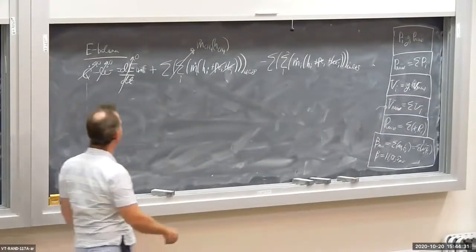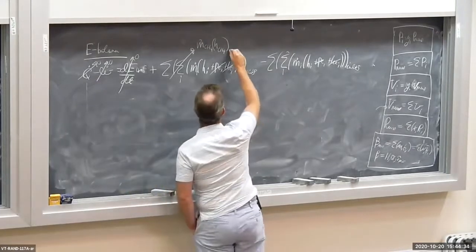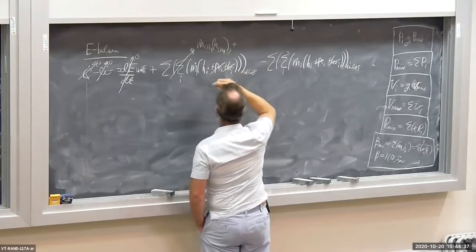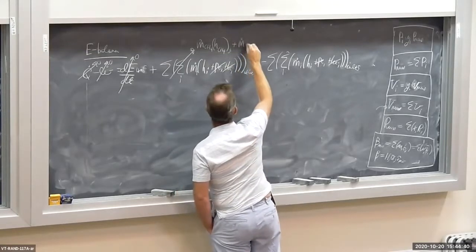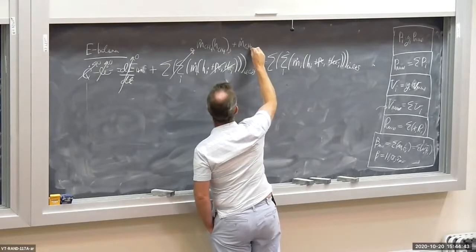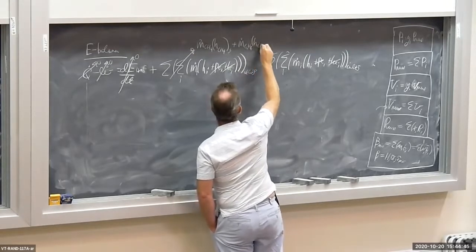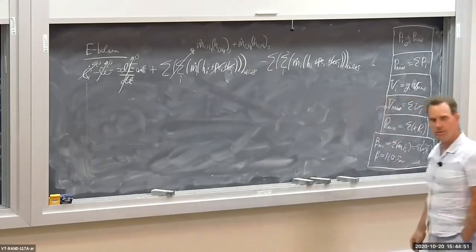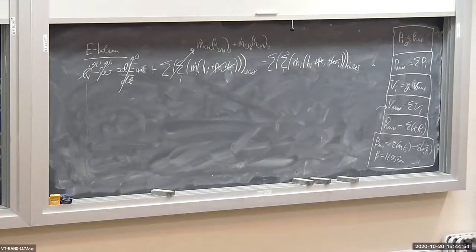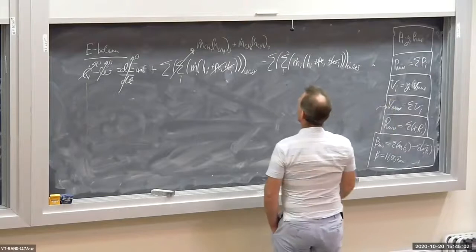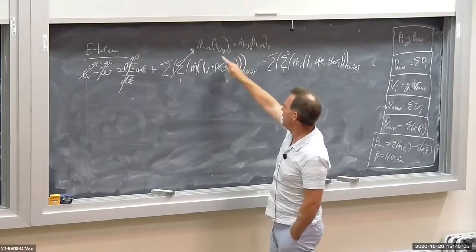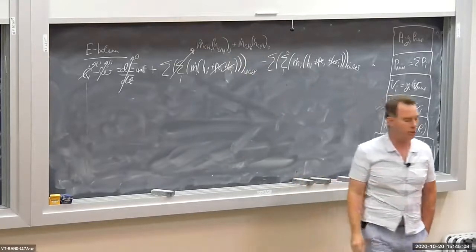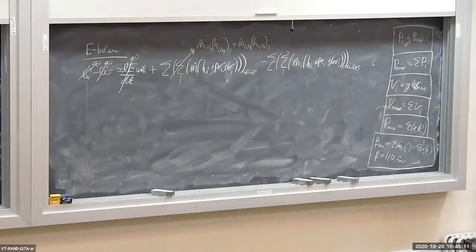So this would be H evaluated at location number 3. I got the ethane as well, so I also have plus m dot C2H6 H C2H6 evaluated at the outlet. The outlet has a certain temperature, therefore the outlet methane and ethane specific enthalpies will have a certain value, okay? So I got 1 outlet and 2 chemical components with the associated enthalpy flows at the outlet.